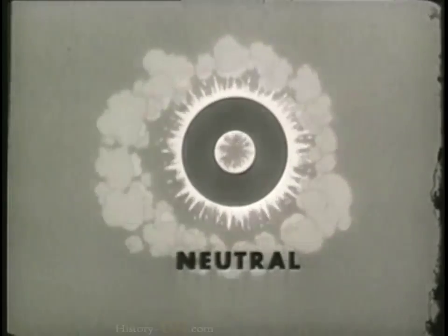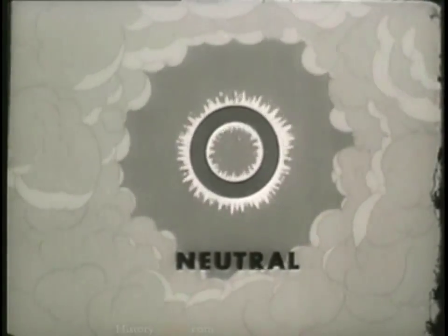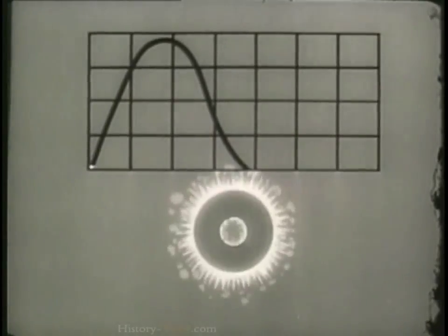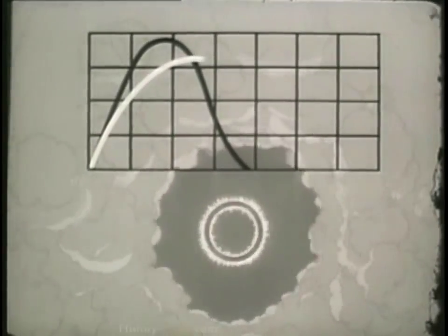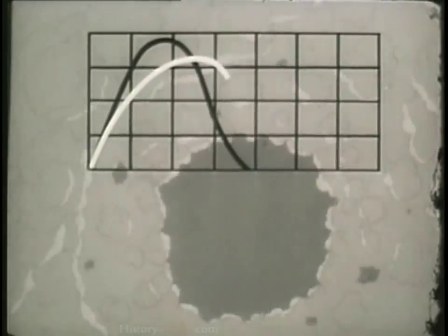In this form of grain, the burning is slower at first, but the burning surface remains constant during the burning period. Thus, the maximum pressure is not as high as with the degressive type, nor does the pressure drop off as sharply when the projectile moves.